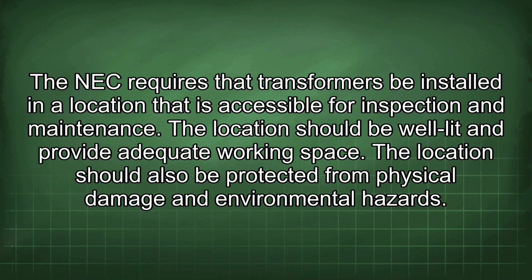The NEC requires that transformers be installed in a location that is accessible for inspection and maintenance. The location should be well lit and provide adequate working space. The location should also be protected from physical damage and environmental hazards.